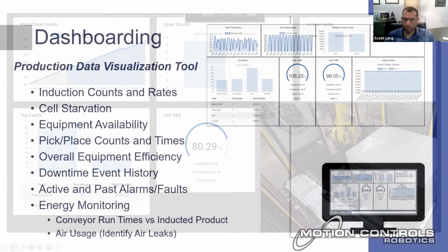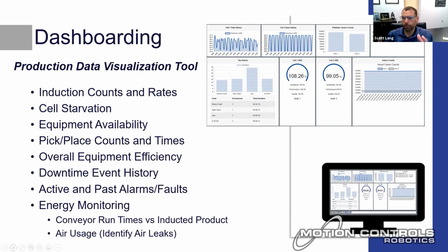One of the things I'm most excited about is the opportunity we're able to change the date and times of the dashboards to bring in more data or less data. So the opportunity to take all the alarms, currently you kind of look at what was the last alarm that we dealt with, you fix it and you move on. But if you can look at it over a week or a month or a year, and all of a sudden you pull in all that data and find out that there is a nuisance alarm that keeps occurring, and no one really thought about it. It happens once a week, but it's causing a lot of downtime. Now you can address something on a larger scale. So I think this is going to be super valuable in that area.